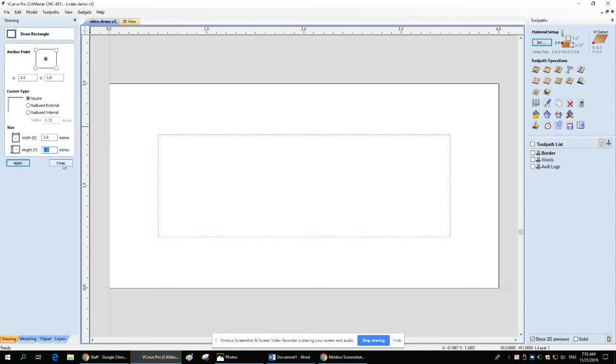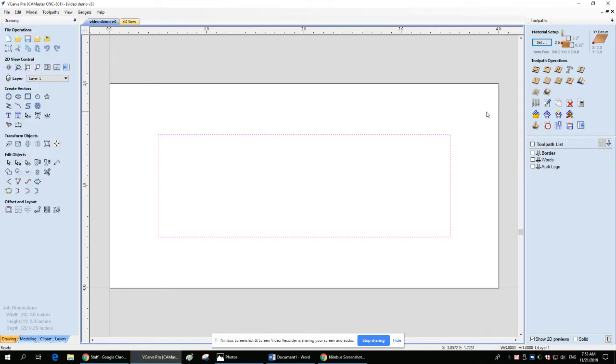I want you to remember those numbers. 4 inches across, but the border's 3. If I start in my origin, I have to go over an inch and up an inch. Then I put the cutter down, and I'll go around over to here, back down and across. So if that's 4 inches across, and I come in, this will be coming over a 1/2 an inch, and this is a 1/2 an inch, so this ends up being 3 inches.